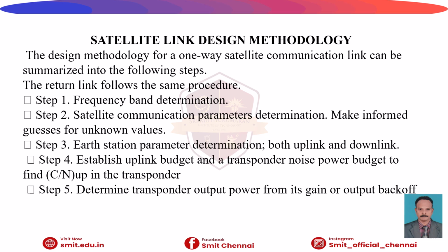So first of all, the frequency band determination plays a very crucial role, since that is the first step we have to follow in the procedure for satellite link design methodology. The first step involves the frequency band determination, since the operating frequency is very crucial, as it directly affects the antenna size, atmospheric losses, bandwidth, equipment cost, as well as the regulatory requirements.